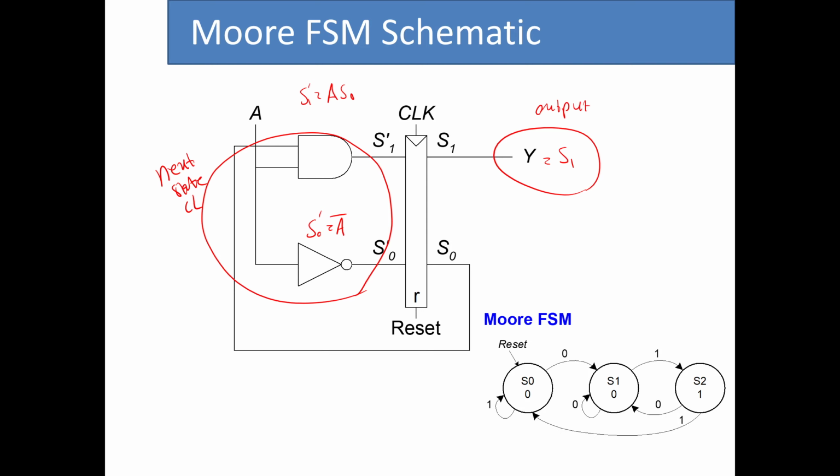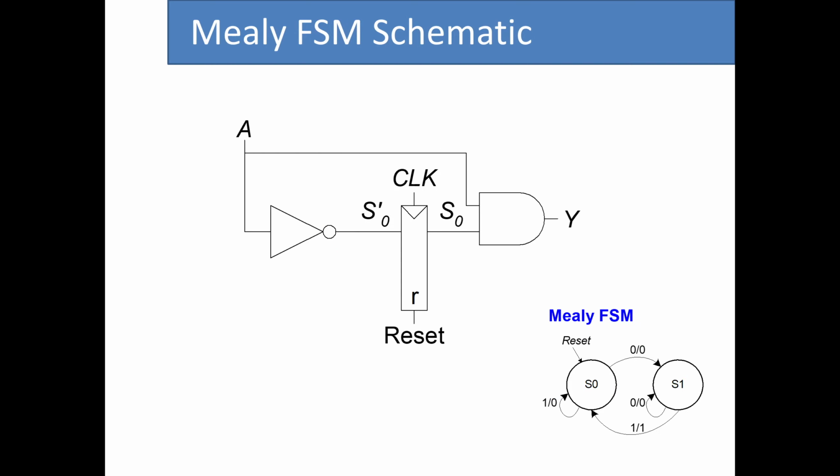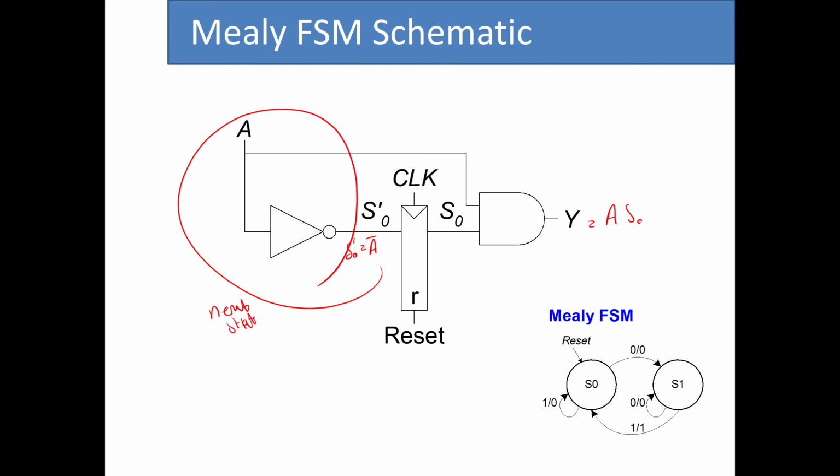As for the Mealy FSM, we came up with equations that were much simpler. For S0 prime, it was A bar, and for Y, it was A S0. So again, this part is going to be the next state combinational logic circuit.